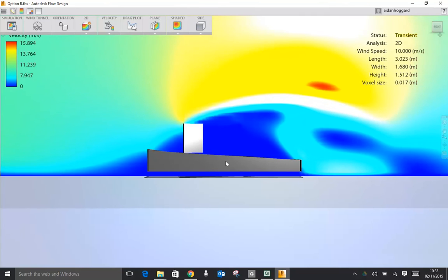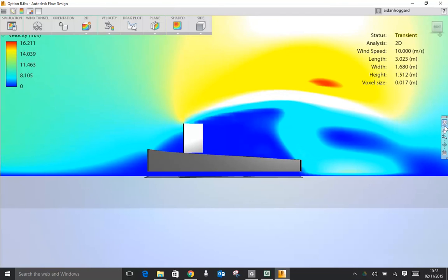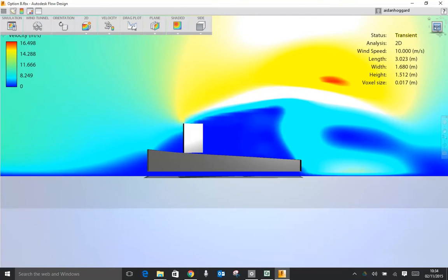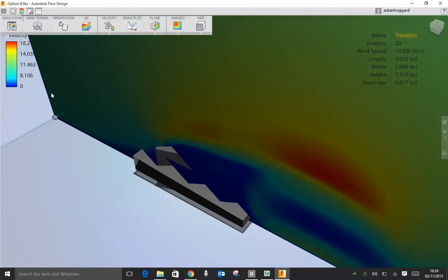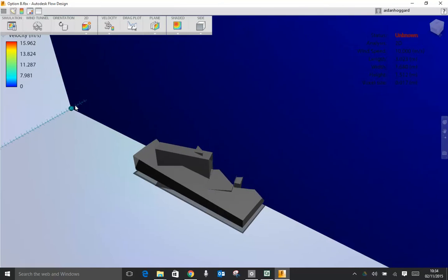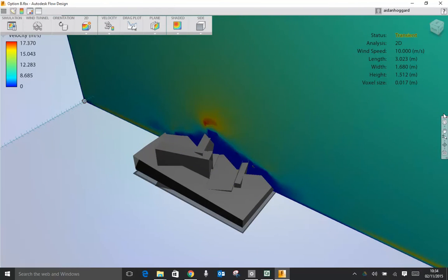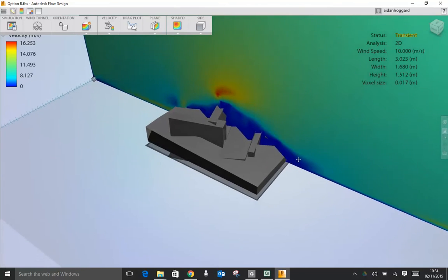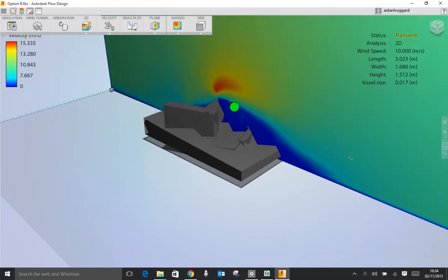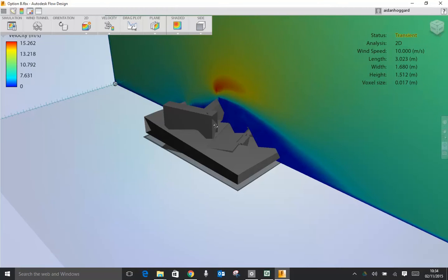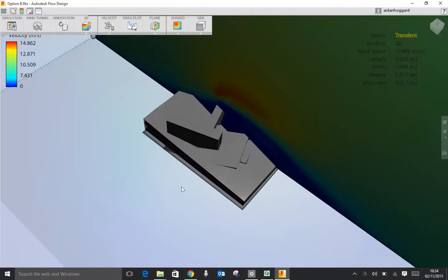Okay, so we're in there. Now, it's a bit faint, but you've got some controls over here. Okay, and you've got a Viewcube, same as in Revit. So same idea, if you click and drag your Viewcube, you can drag your view. Equally, you can use the controls over there. Over here, you've got your usual sort of orbit, pivot tools that you'd be familiar with. When you've activated that, you have to re-click back on the button over here to deactivate it. Okay.